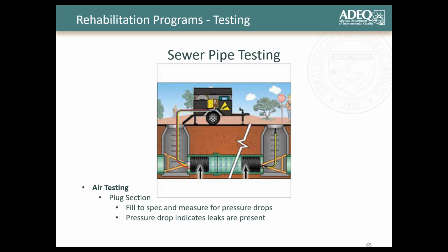But you're right. Ideally, you measure it up to a desired pressure. You measure a pressure drop. Obviously, you have to be careful. You don't want to overpressurize that system and create a break yourself. But you measure a pressure drop over an extended period of time, usually about a day or so. If you drop more than the predetermined acceptable pressure drop, right, 2 pounds of pressure, then there's a leak, or a major leak present, and you have to do something about it.